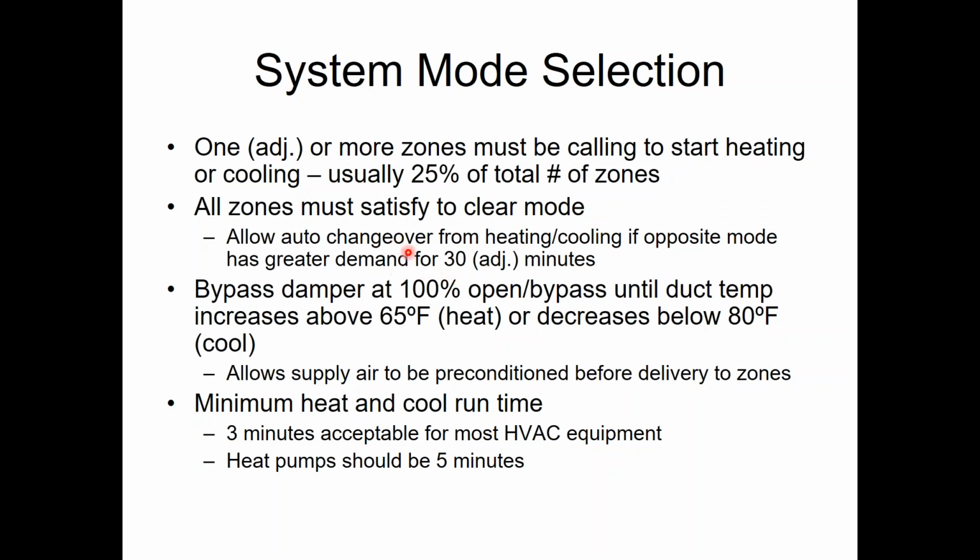Usually I'll put a 30-minute timer in there, and if after 30 minutes we still didn't solve all of the cooling guys' problems or all the heating guys' problems, whichever mode we were in, I'm going to go ahead and take a revote. Like, you know what? We had these 5 guys calling for cooling, and we had 2 guys calling for heat. I went to cooling. I tried to take care of you guys for half an hour. Let's vote again. And when I vote again, maybe it's 1 cooling caller left and 2 heating guys, and now I go to the heating mode.